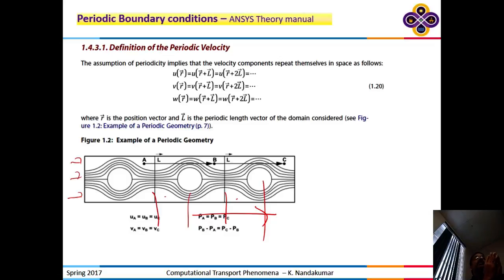Okay? And when you do that, you need to worry about how do I specify the boundary conditions. So here I specified it as an inlet condition. So I can put any velocity profile, and then the flow will evolve from that. Okay? But when I'm isolating a particular unit as a periodic unit, I need to make sure that what I specify here is the same as what I specify there. Okay? So you can identify these 2 planes and say they are periodic.